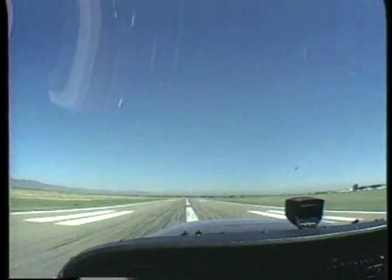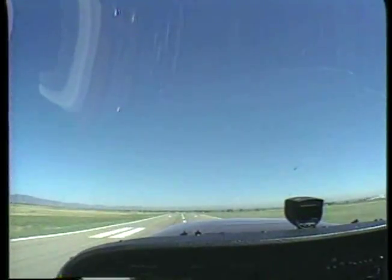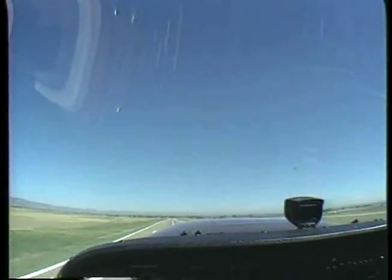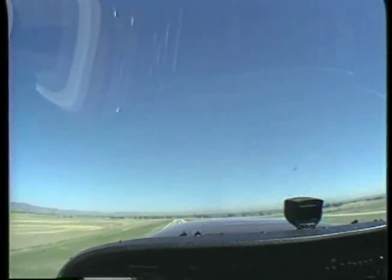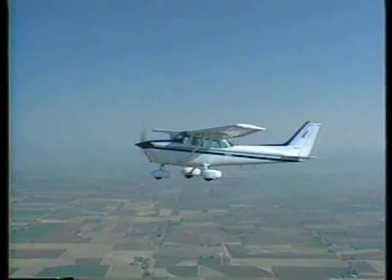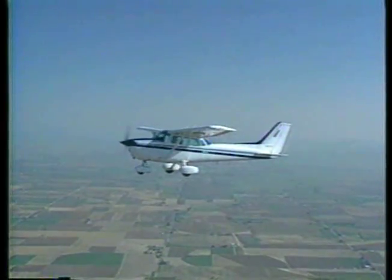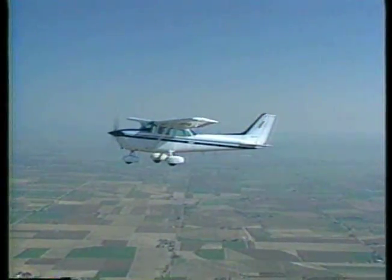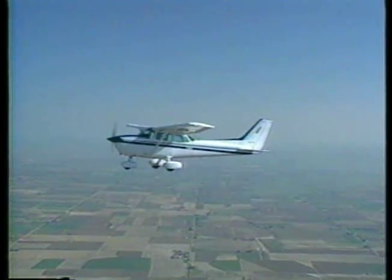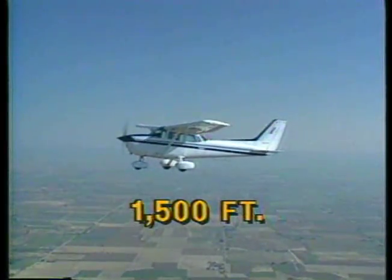A power-on stall can occur if you attempt to lift off and climb out at an airspeed below that normally used for takeoff, or if you use too high of a pitch attitude when trying to clear an obstacle. As with power-off stalls, learning to recognize the sensations and visual cues that precede a power-on stall will help you avoid accidentally entering into one. Remember, you should practice stalls at an altitude that allows recovery at least 1,500 feet above the ground.